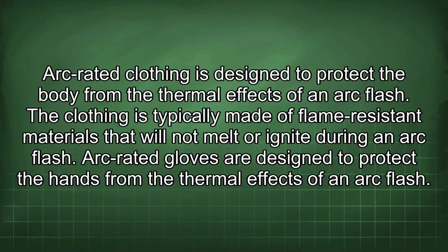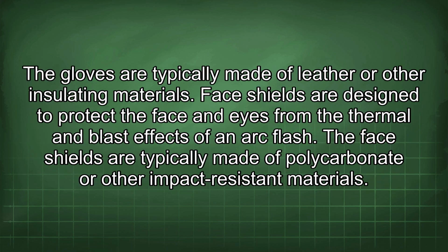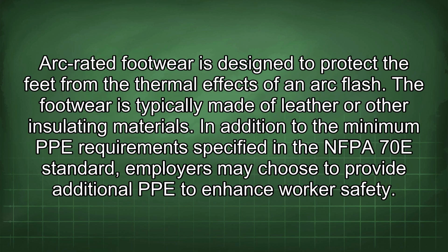Arc-rated gloves are designed to protect the hands from the thermal effects of an arc flash. The gloves are typically made of leather or other insulating materials. Face shields are designed to protect the face and eyes from the thermal and blast effects of an arc flash. The face shields are typically made of polycarbonate or other impact-resistant materials. Arc-rated footwear is designed to protect the feet from the thermal effects of an arc flash. The footwear is typically made of leather or other insulating materials.